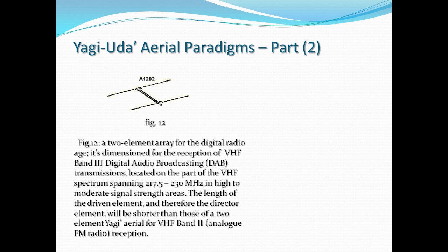The length of the driven element, and therefore the director element, will be shorter than those of a 2-element Yagi aerial for VHF band 2, that's analog FM radio reception. Figure 13 shows a 3-element array for DAB reception in moderate signal strength areas.